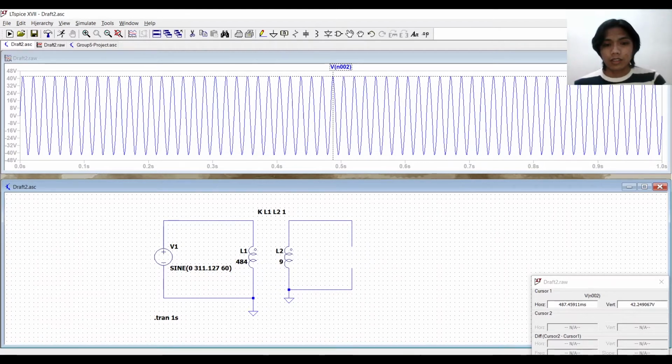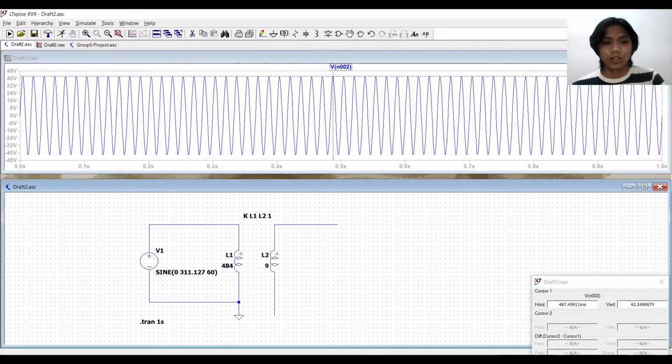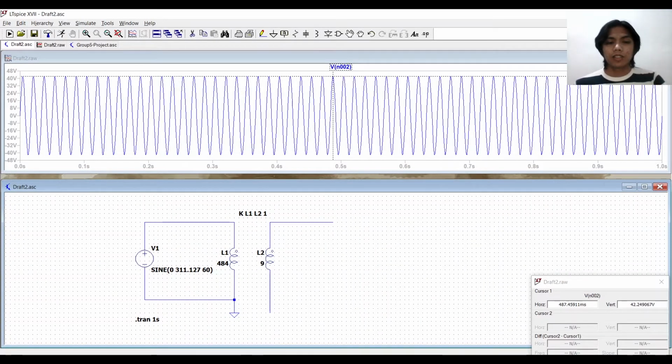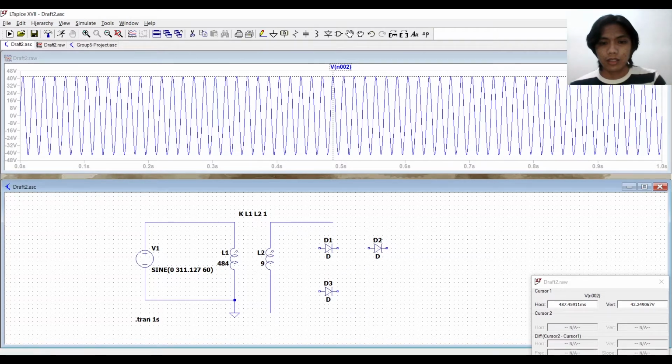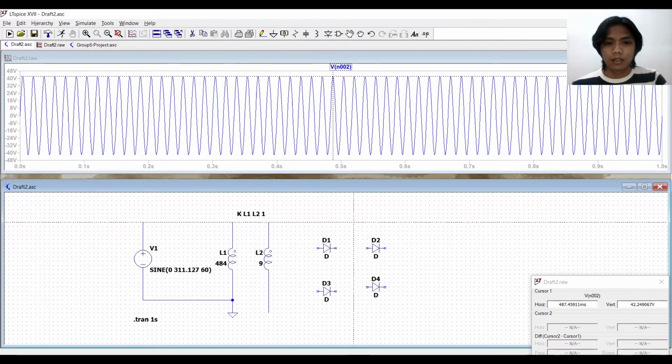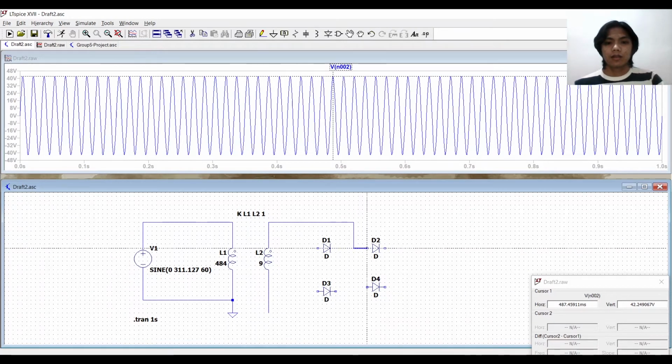Now it is time to construct the rectifying circuit in order to actually make use of the 220 volt RMS alternating current. The way to do that is to use 4 diodes. By the way, the type of rectifying circuit that the group built was a bridge type full wave rectifier, because it is much more efficient than the center tapped one.